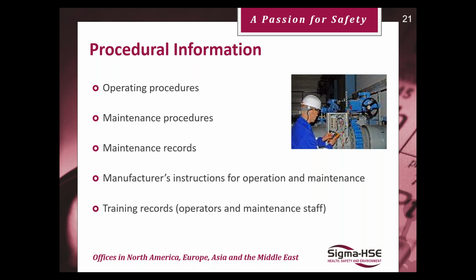Also, yes, manufacturer instructions. So this typically can be found in the manuals. So in your legacy equipment, it may tell you, oh, you may need to grease the bearings at so much intervals or every 100 hours or such. So this is important.